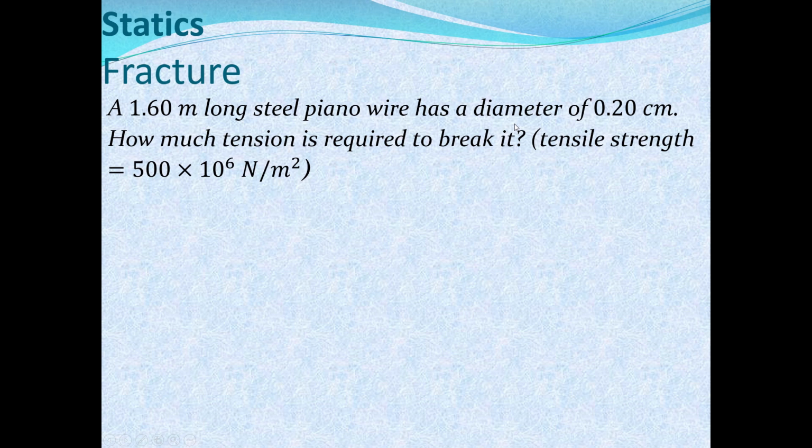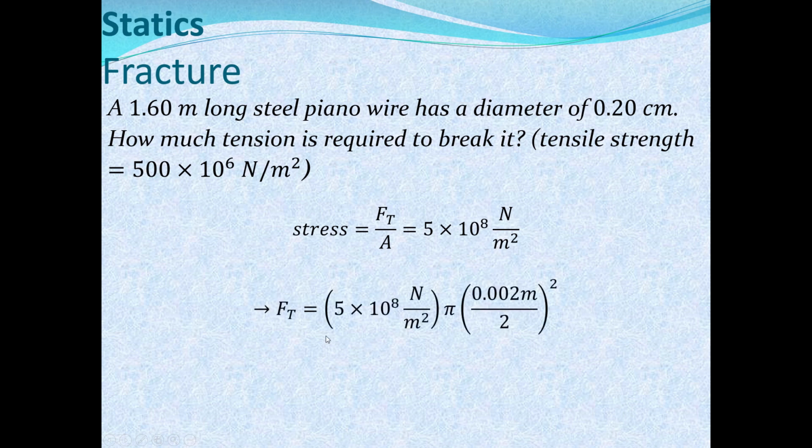All right, so we use the stress from the textbook. I gave it to you here, but the textbook also says that steel has a fracturing stress of 5 times 10 to the 8th newtons per meter squared. So I use this to find that the force required to stretch and break a steel wire would be 1,600 newtons. In our previous scenario, we were applying 980 newtons onto the object, so we're a little more than halfway to that value. So we're actually close to fracturing that wire.